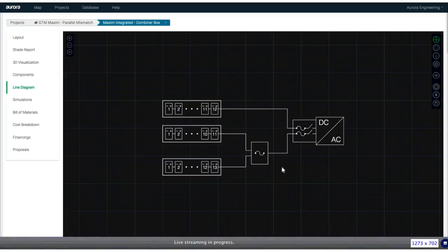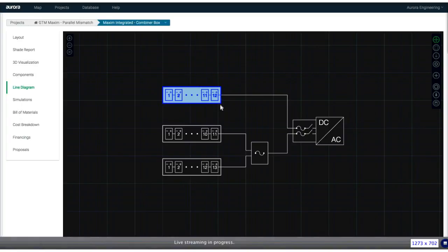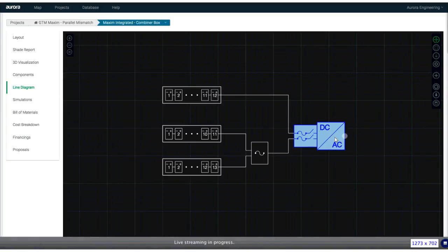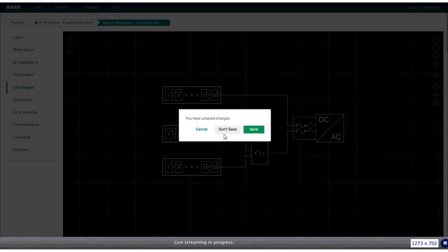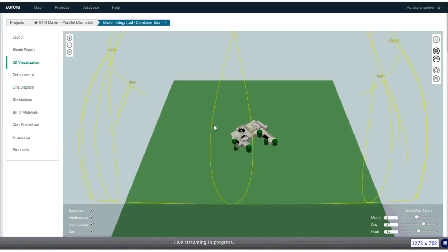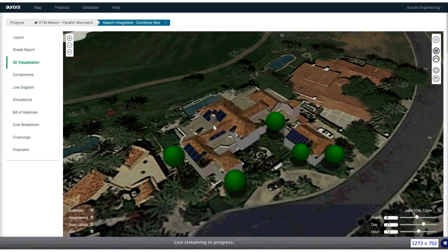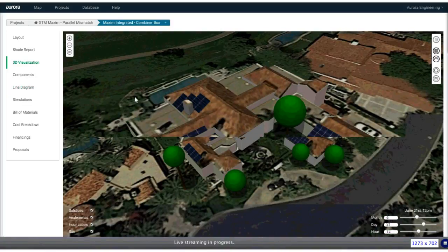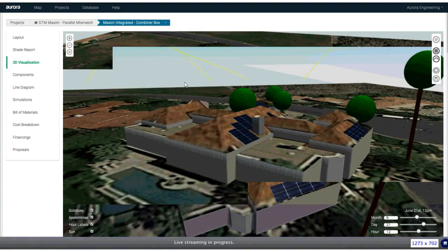So generally, this is not good design practice with standard modules because those voltages will have to equalize, and in so doing, neither string will operate at maximum power. You'll just have an inefficient design. But with cell string optimizers, you can do this, and it won't impact performance. And so those are connected in parallel, go into one MPPT port of an inverter, and we have our other string of 12, which we left untouched, and that's connected to a separate MPPT port on that inverter.